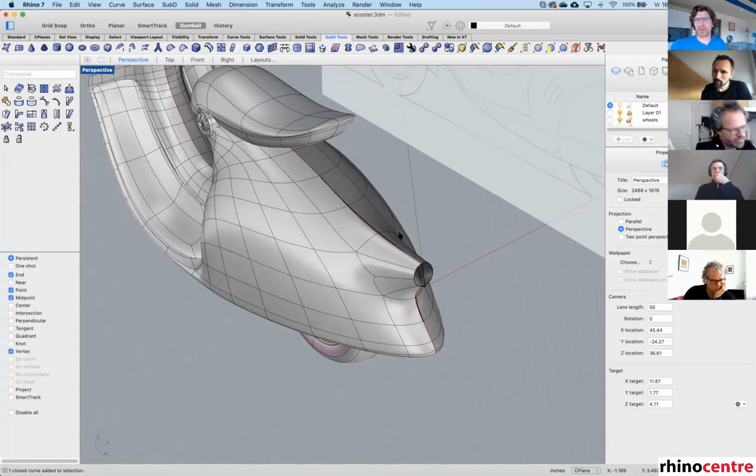I don't think that it's currently possible, but it would be nice if you can directly manipulate the shape of a subdivision surface. So what you want in Grasshopper is that you are able to connect to one control point in a SubD and be able to manipulate it. I think that's the big question. Are you able to locate one control point of a subdivision surface in Grasshopper? Okay, I can probably answer that. The answer is no, because it's not that structured at the moment.